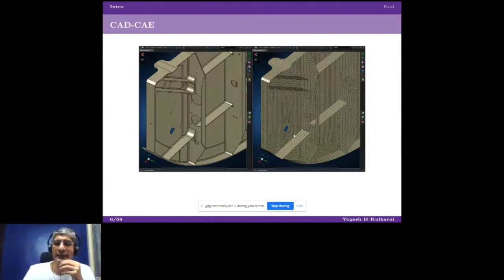And this surface is called a mid-surface. It's in the middle. And I'll show you a couple of diagrams of how it looks. So don't worry if you cannot imagine it as of now. What's the use? If you do a solid mesh, there are so many elements. But if you do a surface mesh, the elements are reduced, meaning the number of calculations is reduced. But the result values, as you can see in the bold, are sort of comparable. They are okay. And the solve time is half.